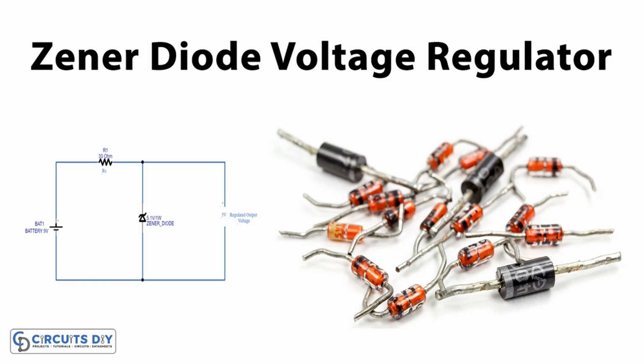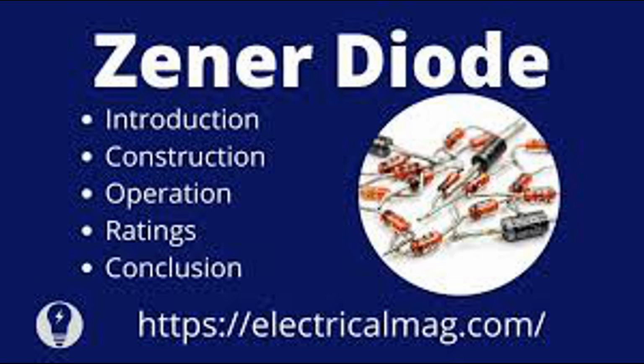7. Breakdown voltage tolerance. Manufacturing variations. The Zener voltage can vary slightly due to manufacturing processes, which is why Zener diodes come with a specified tolerance, typically plus or minus 5% or plus or minus 10%. 8. Breakdown mechanisms. Zener breakdown dominates at lower voltages, below approximately 5 V, due to quantum mechanical tunneling. Avalanche breakdown dominates at higher voltages due to impact ionization.